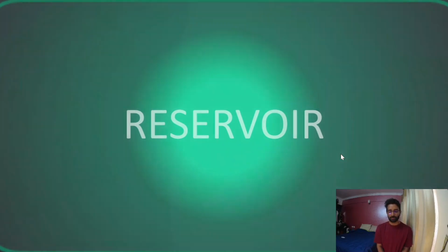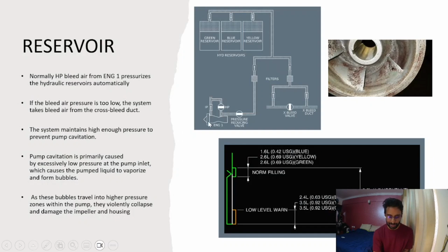Now what about the reservoir? So as you can see, this is your engine 1. There is intermediate pressure and there is high pressure. This high pressure is used by filters. It's used to pressurize the reservoir tank. All three reservoirs are pressurized by the high pressure of engine 1, as you can see on the picture. But if there is not sufficient pressure from engine 1, then a cross split valve opens, which will take high pressure from engine 2 and supply it to the tanks.